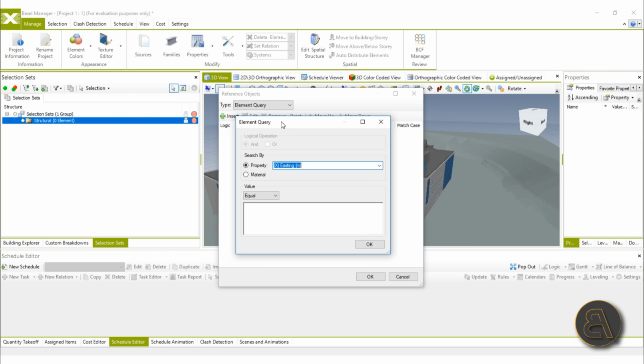First I'm going to set a work set name. In Revit, all of these elements were modeled within some sort of a work set, because this is done as a model, as a linked file. So now I need a work set that has ST in the name. That means structure. So I'm just going to search for work set.